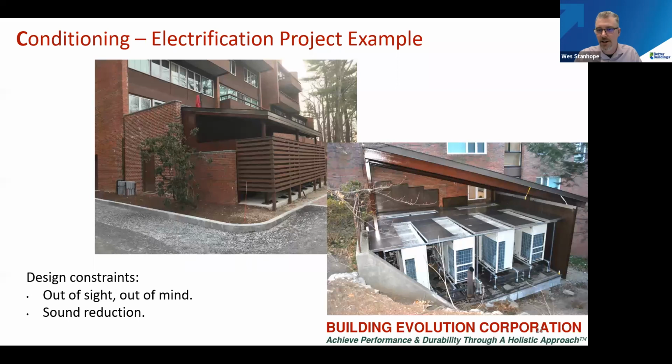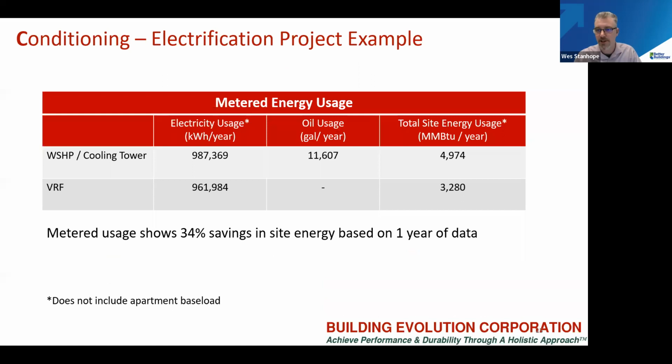This project here is one where electrification was required, but also we had to bring down the sound and the visual impacts. So sound attenuation was added and the VRF equipment was actually hidden, to bring down the impact of VRF. So electrification could be brought into nearly any type of project setting. That same project, the meter data before and after, going from oil and electrical for cooling to all VRF, was a 34% reduction in metered energy.